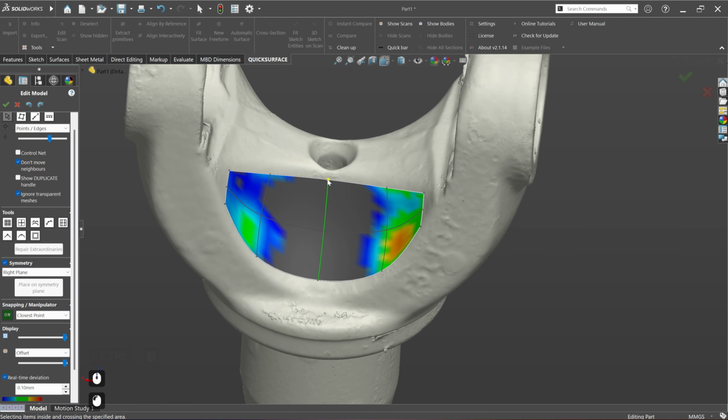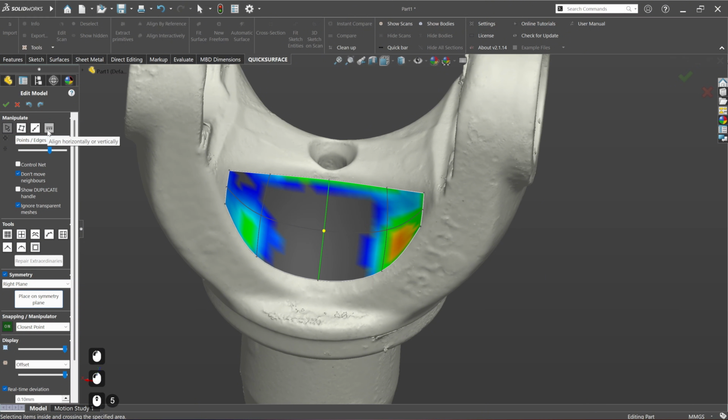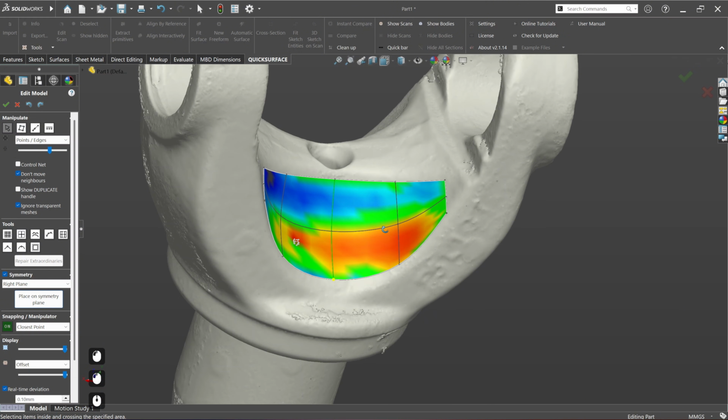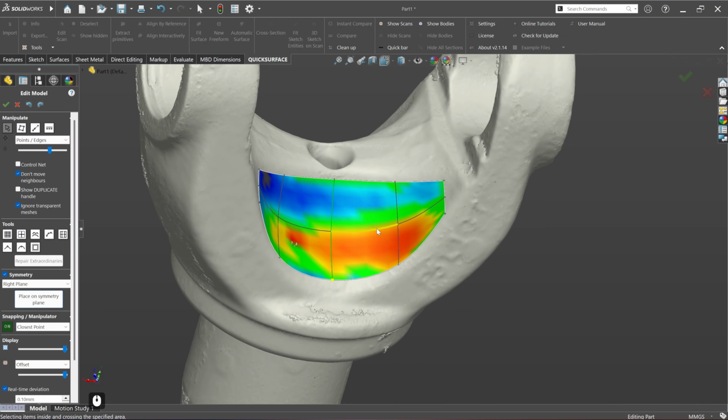So what we can do is come over here to reposition this, or just use the option snap to mesh. So I'm going to select all these points, snap them back. And after this, I want to start to reposition these middle points probably in order to get better deviation.